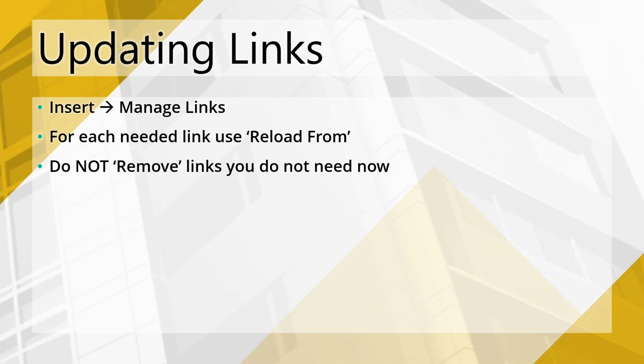Also, all of the links that we've placed in here are already inserted origin to origin. They're already pinned in place. And that way you don't have to worry about coordinating that. Now, if the other design team members are leveraging the proper origins, and hopefully they are, then your model setup is super simple. If they are not, the most important model that you need to pay attention to is the architecture model.